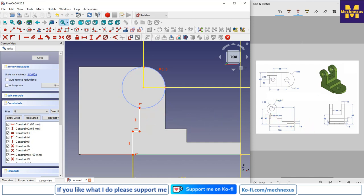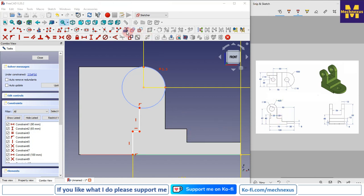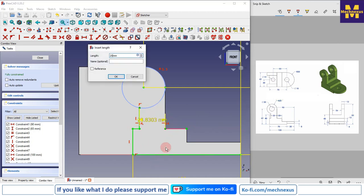So if we see here, this dimension is not given, but we can relate it, we can make it collinear. So for that we will project this edge and make this point and this point horizontal, and this point and this point give the horizontal dimension 25.